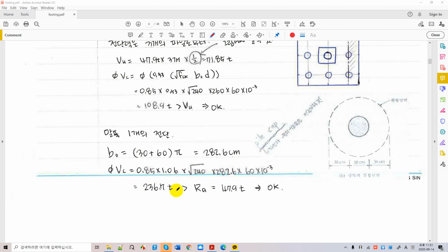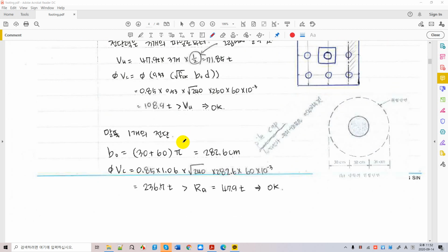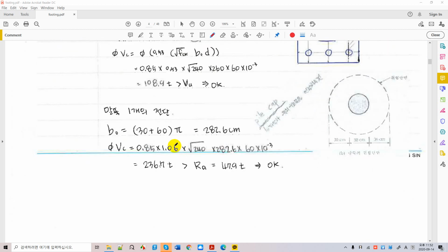Now we have here the shear capacity, and the shear force acting on one pile will be smaller than this value, right? So the two-way shear, considering the one-pile failure criteria and failure parameters, is now greater than the shear force provided by one pile. So we are all okay. Two-way shear, one-way shear, and two-way shear by one pile.